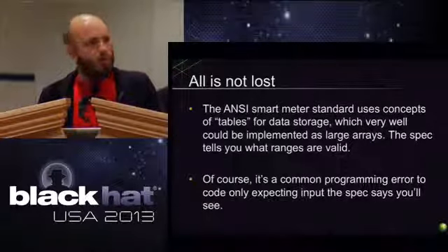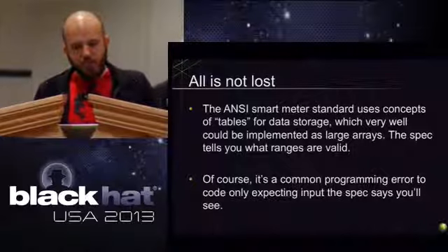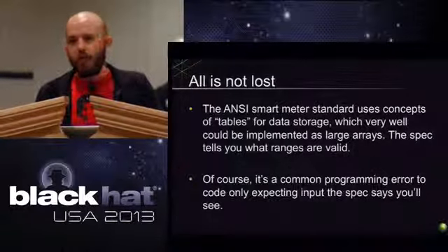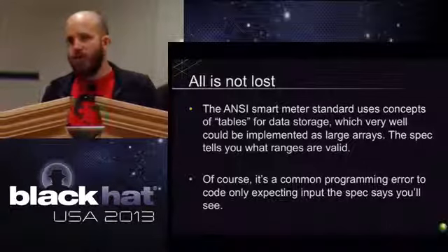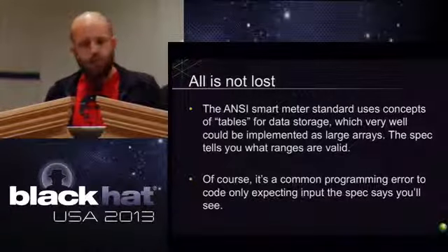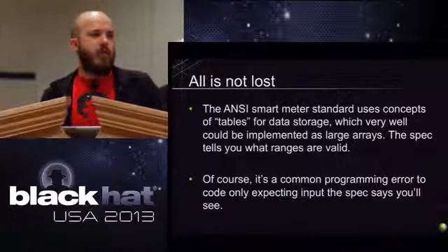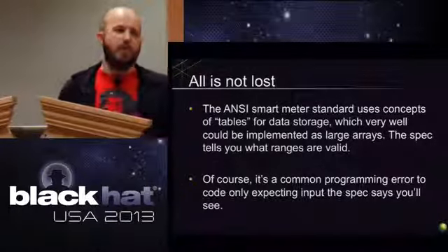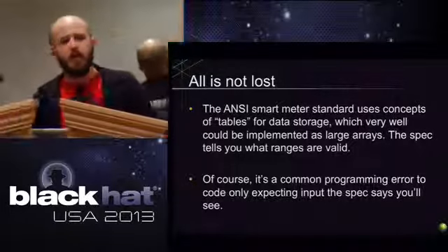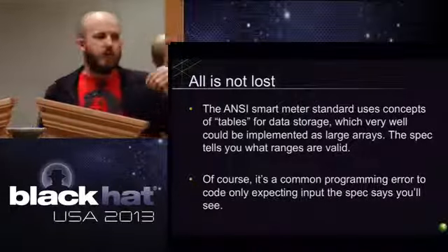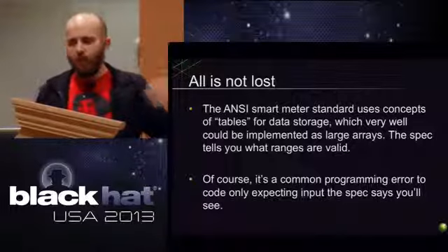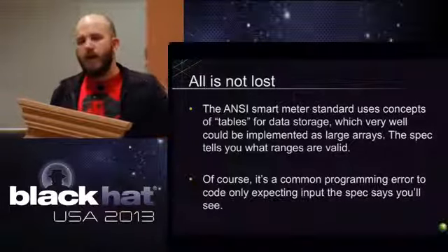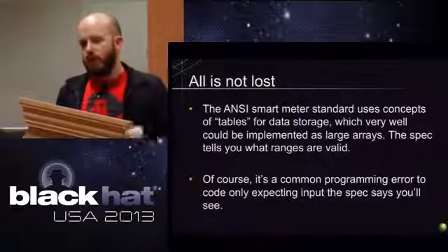But let's talk about the ways that you might be able to do this, and the ways that we'll demo here in a minute. So the ANSI Smart Meter standard uses a concept of tables, right? If you saw Cutaway's talk, you know all about this stuff, or if you've seen one of the other ones. It's when you're reading memory out of data or reading memory off of a meter. Let's say you want to know how much power usage has been used over this period. What you do, via the standard, is you ask it the right way to say, hey, give me the contents of table 10, whatever. And then if you've got access rights to do that, it'll give it to you.